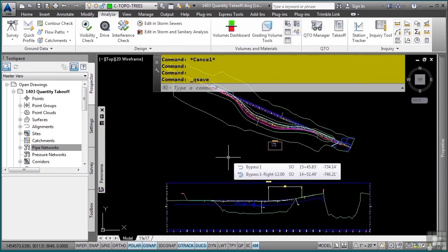You can add quantities to your drawings using Civil 3D's QTO Manager to apply pay items to AutoCAD Civil 3D objects or regular AutoCAD objects. Incorporating pay item information correctly into design plans, including plan sheets, summaries, and bid documents, is a major task for designers. You can use the QTO Manager functionality to automate the pay item process to reduce those errors. Pay items can be associated to AutoCAD lines, open or closed polylines, blocks, or any AutoCAD or Civil 3D object after they have been created.